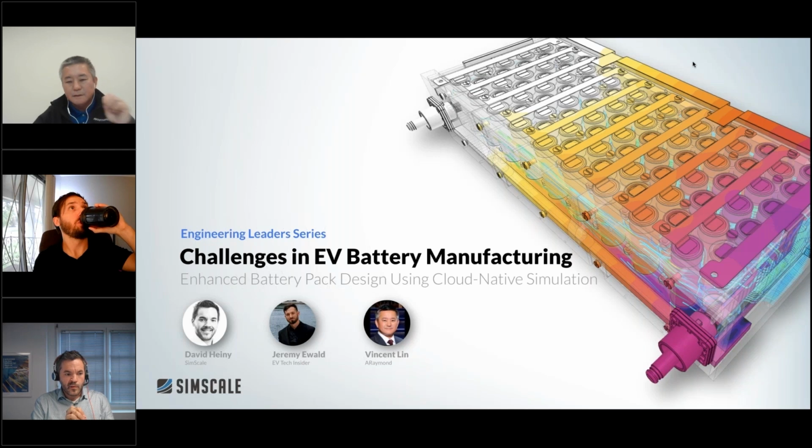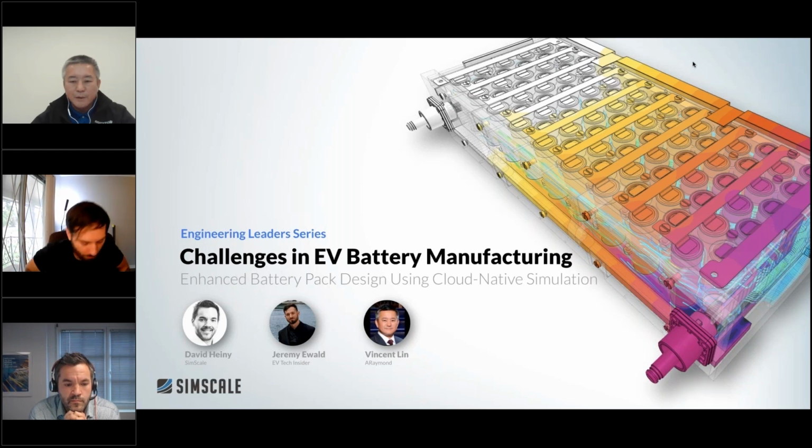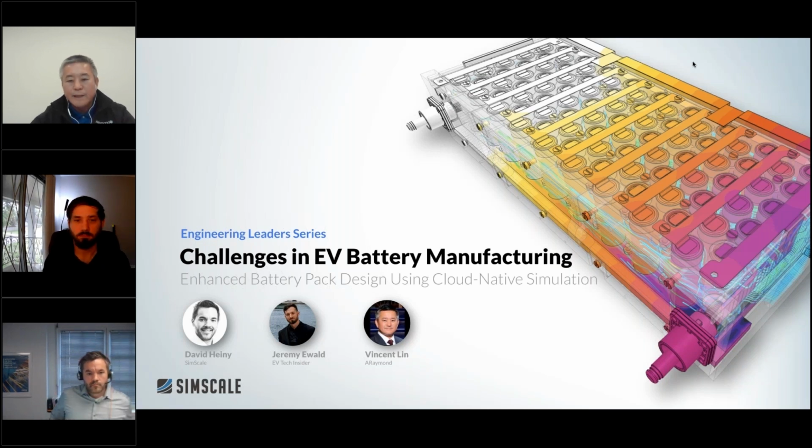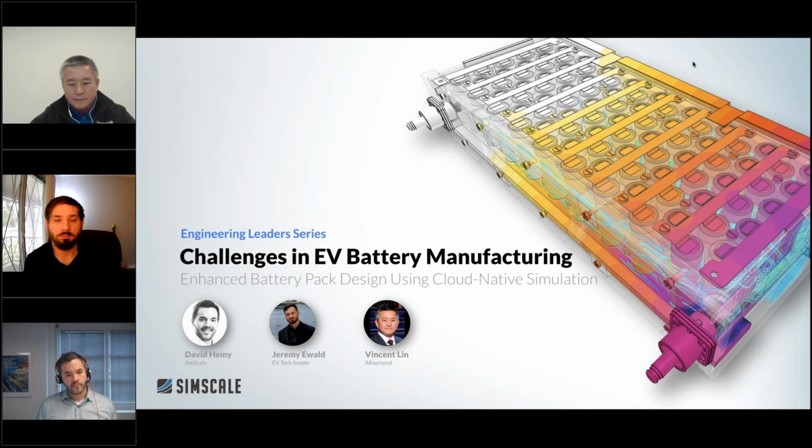Yes, so from the high power connector industry, the bottleneck of your resistance is your contact resistance on that contact surface. And we have been seeing several simulation software, which is a simulation work done, which does not consider the contact interface resistance.